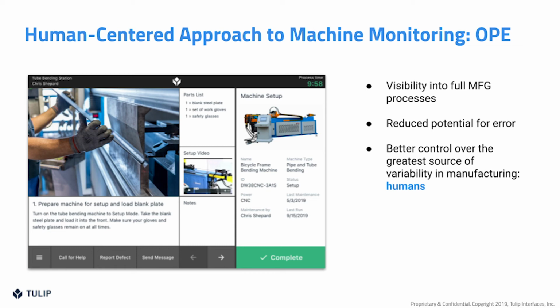Yeah, one of the previous points I brought up before was those downtime reason codes. There's also when the machine gets ready for changeover, say it's a spool wire machine. The end of the spool runs out, it trips the low limit sensor. The work instruction can also be automatically triggered on the HMI screen to go to a video showing that operator how to load the next wire spool and giving them directions to run their barcode scanner for traceability against the material they're putting in. And then that's all recorded right then, right there, in real time.